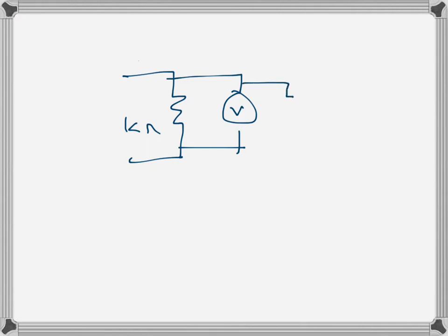If we want to calculate, maybe with this voltmeter we could have calculated resistances of a few hundred ohms, because then the parallel combination would be much less, so the current that the voltmeter would draw will be much less in that case. So let's say we want to calculate a 1 kilo ohms resistance. So here is 1 kilo ohms, and the voltmeter that is connected across it has an internal resistance of, let's say, 100 kilo ohms.